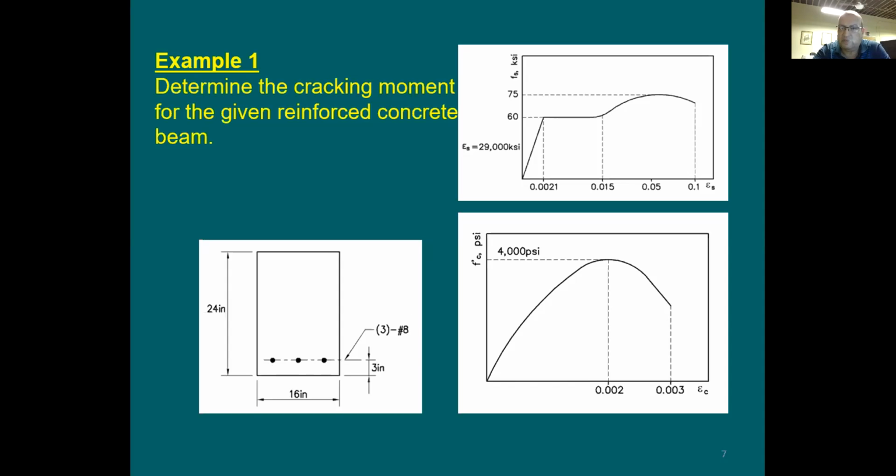So I don't want someone to go and read about it and start to think, say, you put some material in there and then you say you can ignore it. I'm going to say yes. For the sake of this analysis, this can be ignored because the effect is going to be minor. So I don't want to get involved with the rebars at this point. This rebar is really going to be activated or triggered once the entire area here starts to crack, and this rebar is going to start to take some tension force.